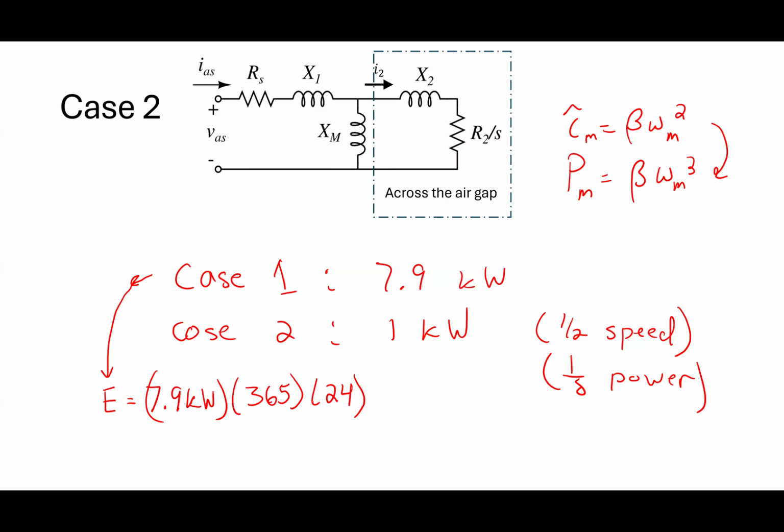The important thing is, I used a number that's somewhat higher than what you'd see in North Carolina, but I did it in the homework: 10 cents a kilowatt hour. At home, you're probably paying 10 cents a kilowatt hour. An industrial customer with a 10 horsepower motor is not paying that; they're probably paying more like 6 or 7 cents.